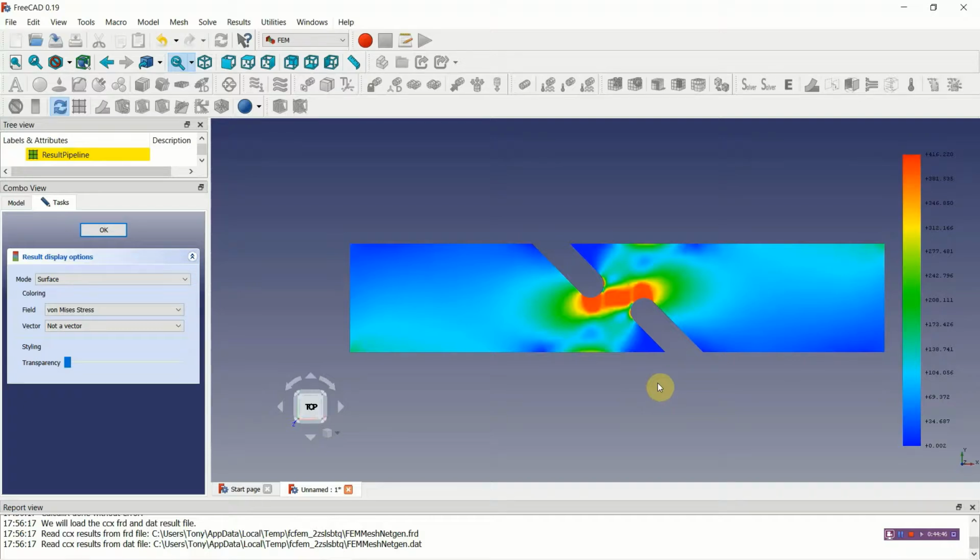I hope that gives you some idea how we set up a problem with the CAD, the meshing, the analysis for a linear problem. You don't have to make any changes to the data set, it will run. If you want to do a nonlinear analysis, then you have to go into the editor, edit in some information like this plasticity curve, and then the analysis will work. So as I say, I hope that gives you a reasonable introduction. The next tutorial I'll move on and I will do something on thermal analysis.